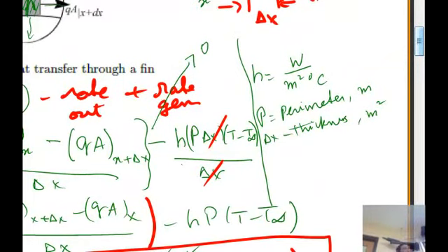That's a convention in the Fourier's law, to make sure that when dT/dx is negative, that is the temperature is decreasing in the increasing direction of x. The temperature decreases as distance increases, the derivative is going to be negative. So the heat flux is positive always in the direction of decreasing temperature. And so the flux will have a positive sign.